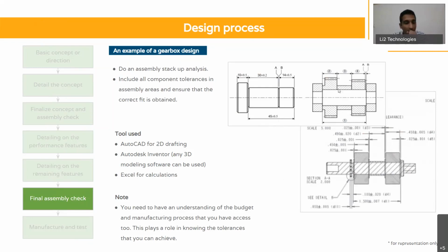And in the worst condition also, you should make sure that this gear doesn't come out of the shaft, else you can't put this end spacer at the end. So that's how it is. So this is a typical way of doing a stack analysis.